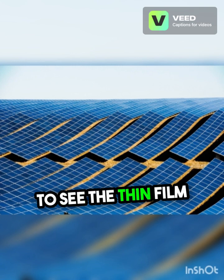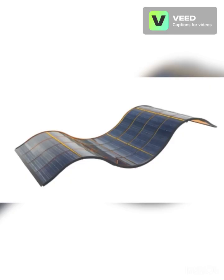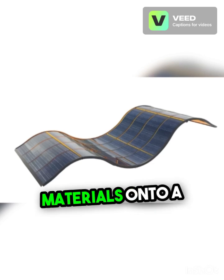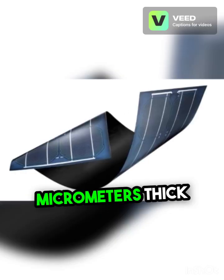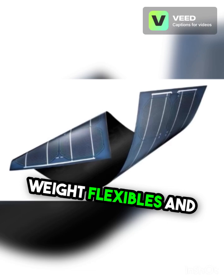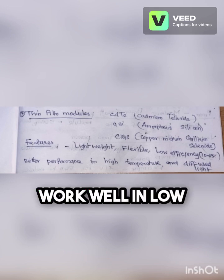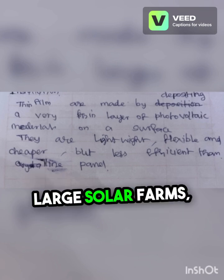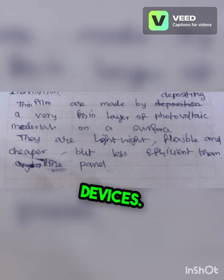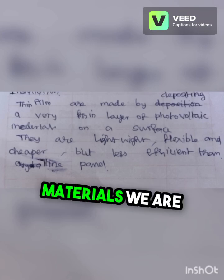Next we are going to see the thin film solar panel. It's a type of solar panel made by coating a very thin layer of solar absorbing materials onto a surface like glass, metals or plastics. These layers are only a few micrometers thick, so the panel becomes light in weight, flexible and cheaper to produce. Compared to traditional silicon panels, thin film panels work well in low light and high temperature conditions and are commonly used for large solar farms, building surfaces and portable power devices. It's cadmium telluride, amorphous silicon, copper indium gallium selenide. These are the materials we are using.